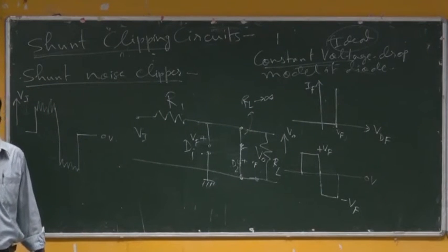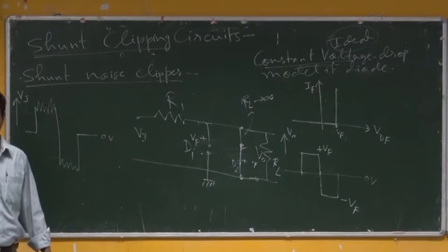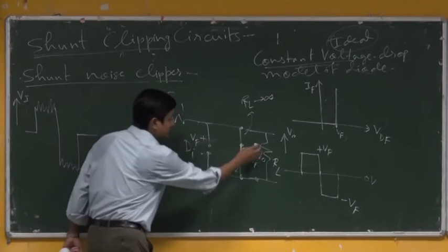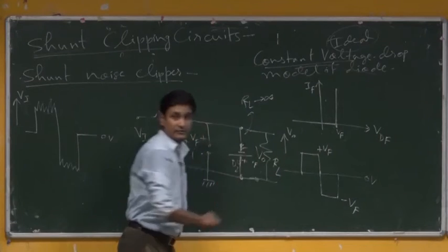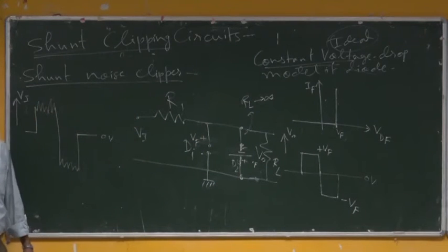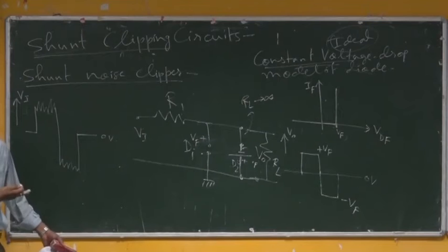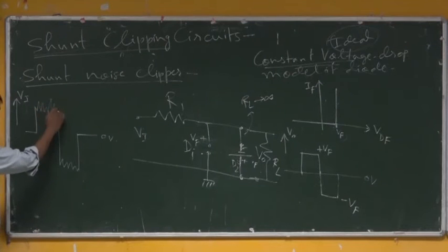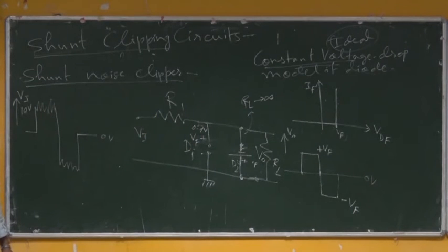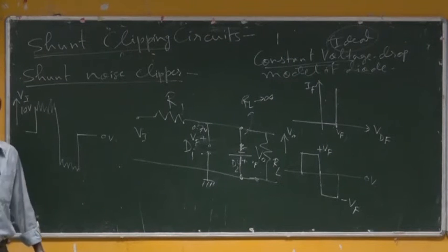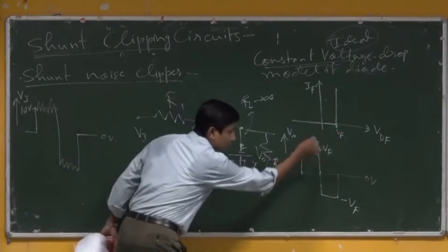This is quite obvious. Actually, I wanted to come to that discussion, that if the connection is like this, which is dependent on that voltage VF, then the output voltage is VF. But is it always possible to accept this kind of circuitry where I am going to remove the noise from here, where this voltage may go up to 10 volt and VF may be 0.3 or 0.7 volt? So, actual sense is gone. Only thing you could do, you could remove the rippling there, which was supposed to be a constant level here, you are getting the constant level there.